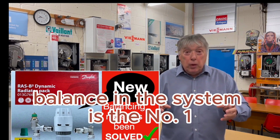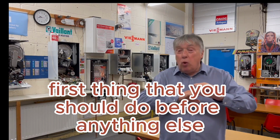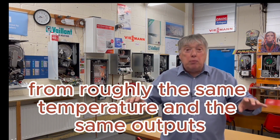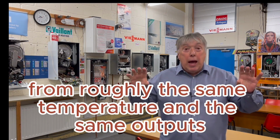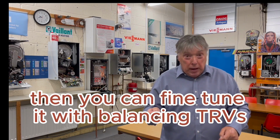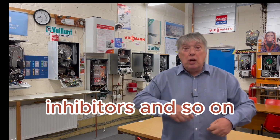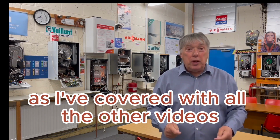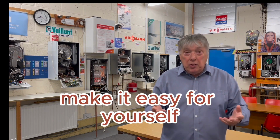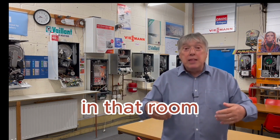Balancing the system is the number one first thing that you should do before anything else. Have all the radiators singing from roughly the same temperature and the same outputs. Then you can fine tune it with balancing TRVs, automatic bypasses, inhibitors, and so on, as I've covered with all the other videos. So download the app, make it easy for yourself, and then see if it's got the right size radiator in that room.